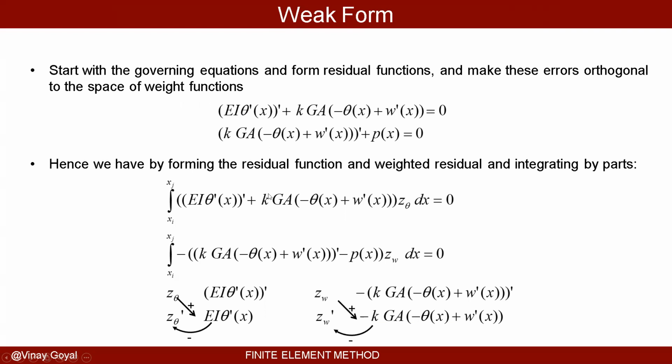Individually, I'll take each equation and multiply by a weight function. Here I multiply by z theta. I've been using V in the class, but it's okay to use different variables as long as you know what you're doing. So the residual function was created for the first equation. The residual is also formulated for the second equation. You can see that here. We're multiplying that by z theta and zw. You can see that there. And then we'll integrate over the domain and equate that to 0.